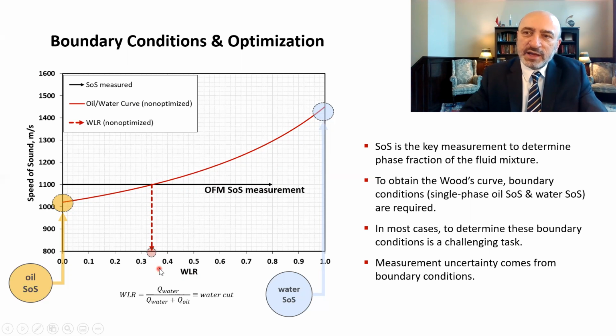Now, this is the inline water cut for downhole conditions, and it is different from the standard water cut at the surface conditions. The definition of the water cut includes an oil term, and the volume of oil for downhole and surface conditions is different due to the differences in pressure and the released gas from the oil phase.